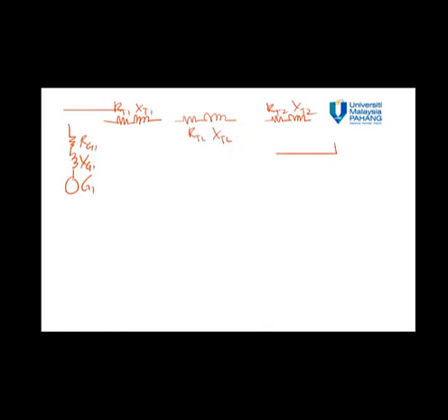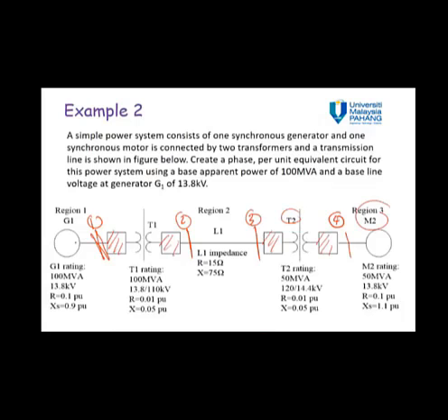So the motor we can represent by this. Just ignore this straight line. This straight line automatically came out when I tried to draw. I don't know why, maybe because I pushed the wrong button. So we have the motor as an inductive reactance XM, and these are all the components available in this single line diagram: G1, T1, transmission line TL1, T2, and the motor.